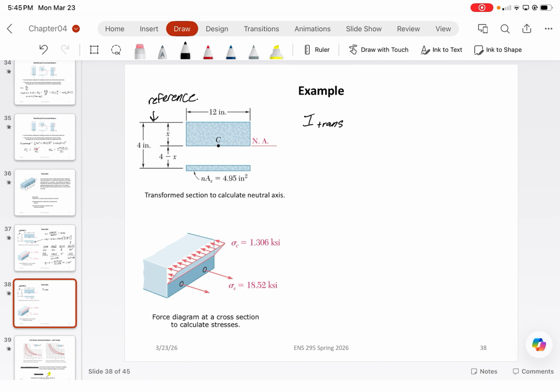So everything is just going to equal our value for concrete. So what we need is a component tab, our area tab, which is going to be in inches squared, a dy, an Ix term, inches to the fourth, and then an A dy squared, inches to the fourth.